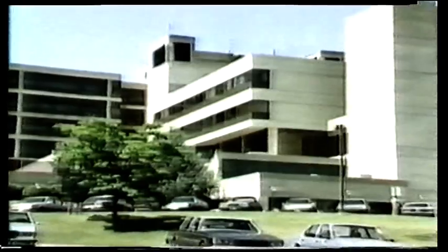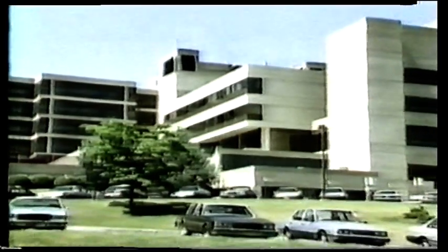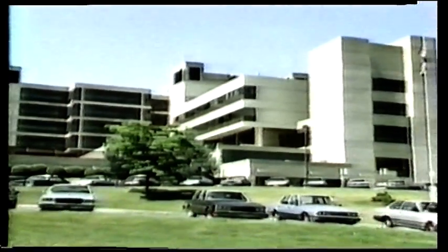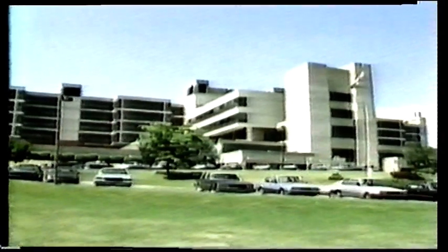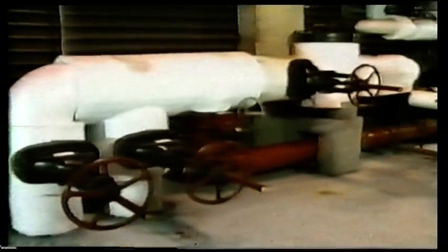While there are many possible cross-connections in commercial and industrial facilities, a hospital was selected for this training video because it provides significant examples of typical cross-connections. Once the survey team has met with the hospital's director of facilities operations, reviewing all key information such as as-built drawings and the critical questions regarding water usage, the actual survey of the hospital begins at the water meter and will follow the water flow through the facility.